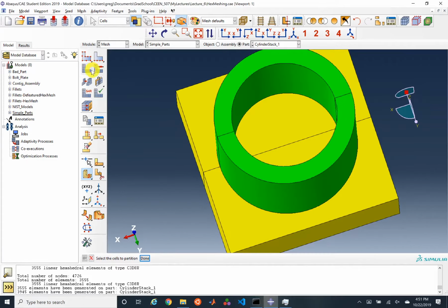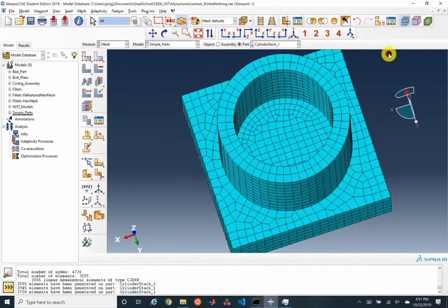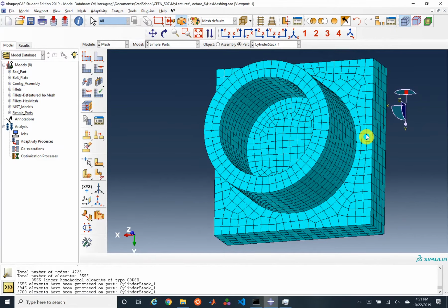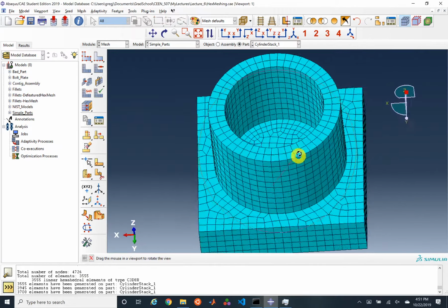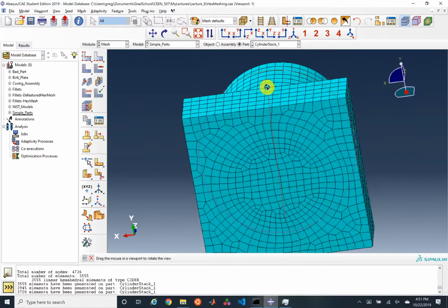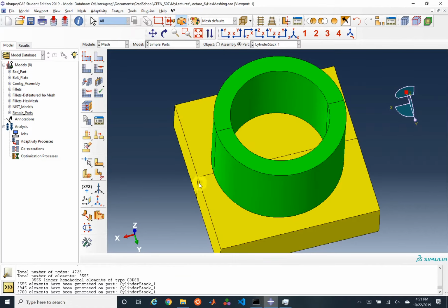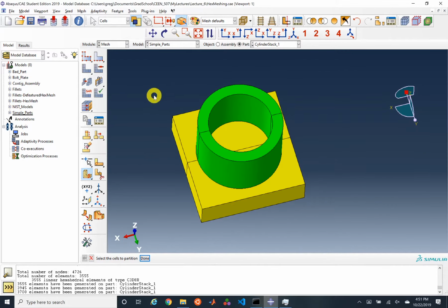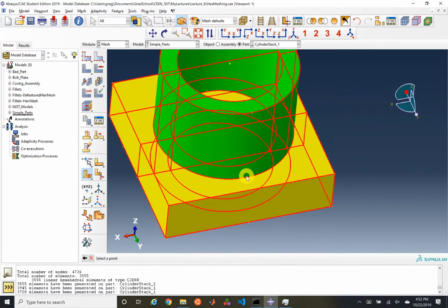Okay, that doesn't seem to have changed very much. If we mesh this geometry, maybe it looks a little bit prettier. It actually looks a lot more beautiful along this surface here, but again, it looks kind of ugly along here. It made sense that earlier, when we partitioned along here, we got good hexahedral matching here. So let's decompose everything by maybe the other direction.